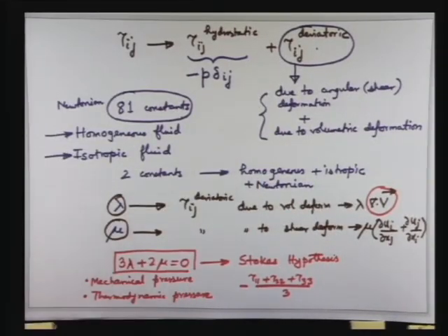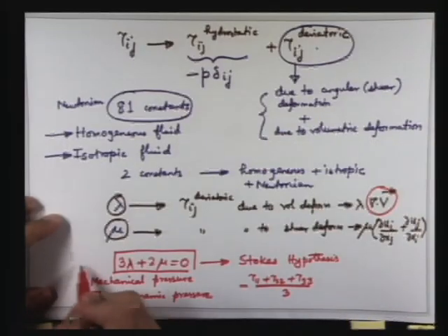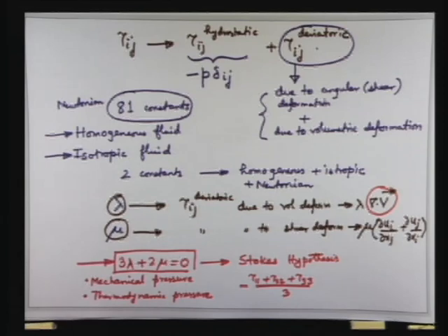But fortunately, fluids are remarkable materials. Typically, most fluids have very quick relaxation. That means the relaxation time is very, very short. It is so short that no matter what the time scale of the disturbance we impose, it will quickly adjust to that. So for most of the fluids and most of the situations that we encounter in practice, Stokes hypothesis is valid. That makes it a remarkable hypothesis. It cannot be directly proved, but the practical situation of time scales demands that the mechanical pressure and thermodynamic pressure are equivalent, so that we can write this.